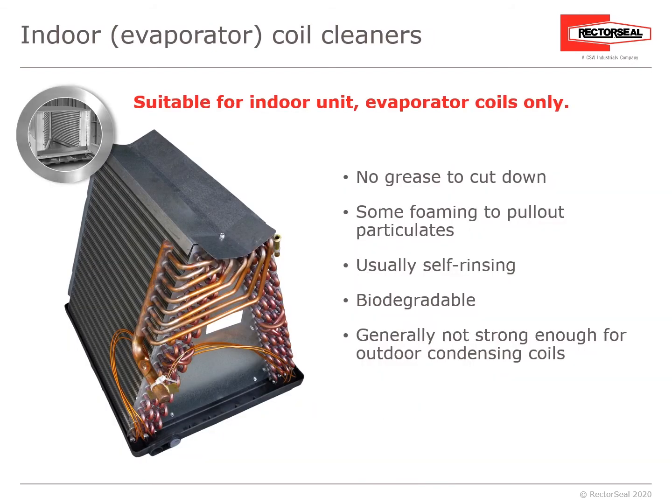Now let's talk about indoor evaporator coil cleaners. A cleaner that is suitable for the evaporator coils only. Generally, you don't have a lot of grease to cut down. You want some foaming to pull out particulates. The product is considered self-rinsing. And of course, you want a product that's biodegradable. But an indoor evaporator coil cleaner is generally not strong enough for outdoor condenser coils.